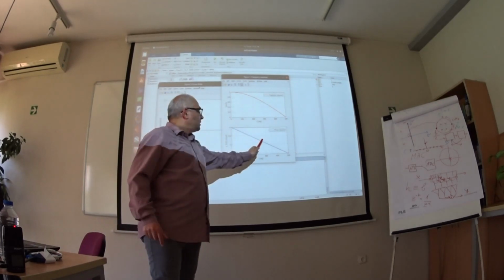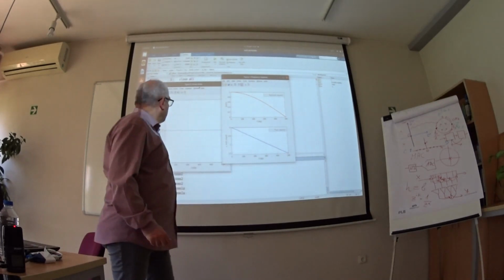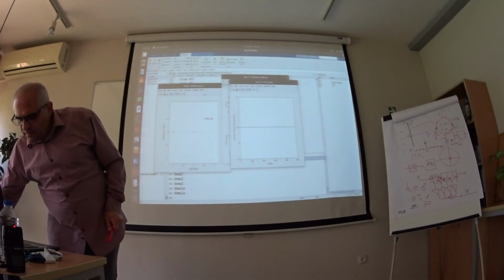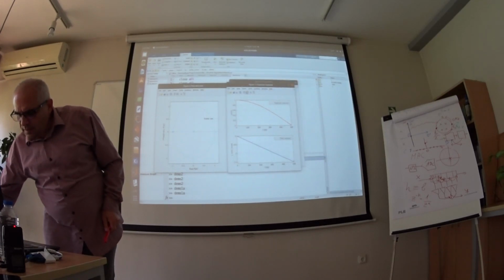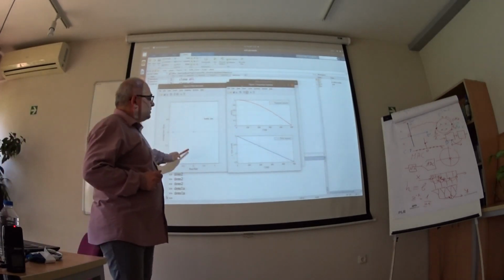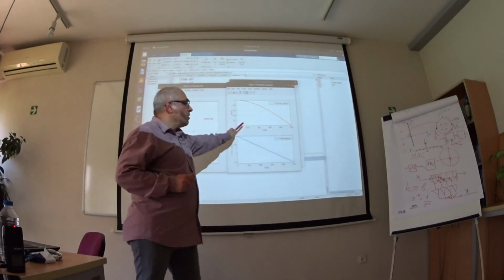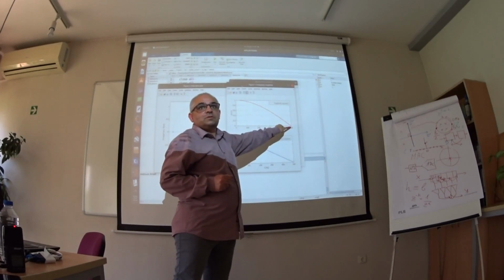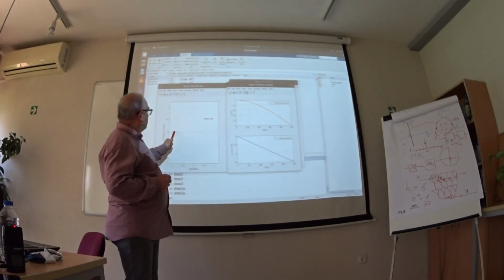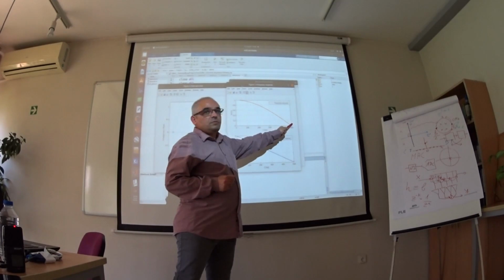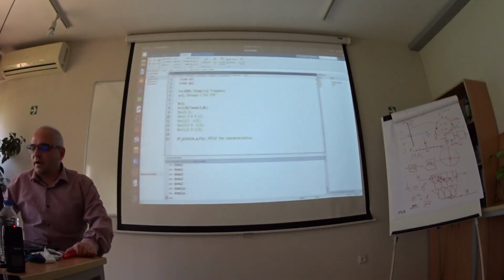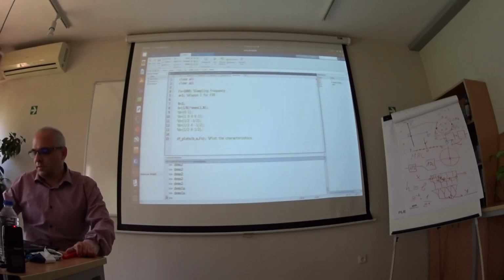Magnitude response, linear phase response, group delay response, and pole zero plot. Can we associate this zero with this magnitude response? Of course. Our sampling rate is 1 kHz. Here is the half, here is the Nyquist frequency. And this zero corresponds to this here. We can make an average of, let's say, 5.